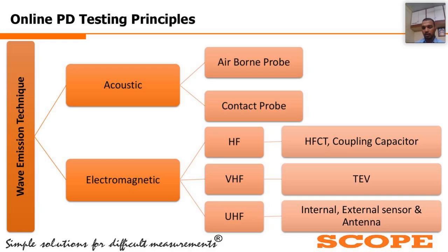They are pre-installed. They are installed in their factories, and then delivered to the customers. And they have a common terminal. So whatever partial discharge equipment you are buying, if your GIS is pre-installed with the UHF sensors, you don't need to worry about its compatibility with any other kit. Most of them have a standard N-type terminal, and every kit will be compatible with this particular sensor.